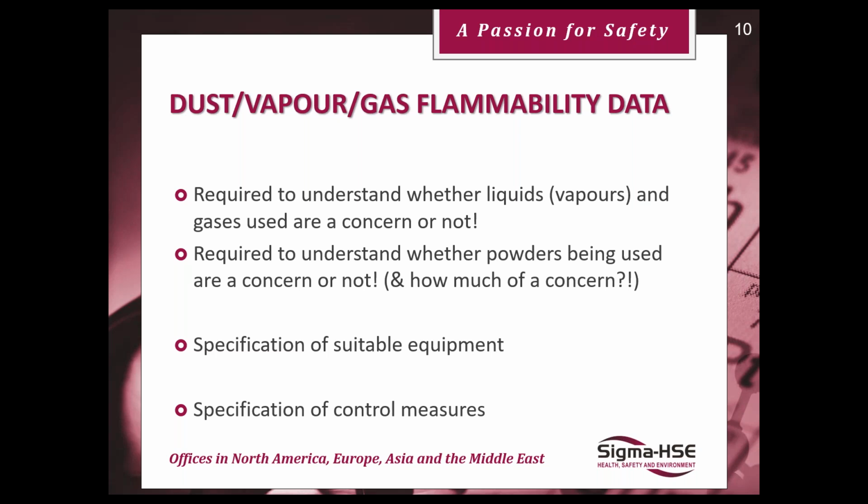And this is where you'll have heard about ATEX certified equipment, ATEX switches, ATEX valves. These are all built to a specification that reduces their probability of ignition. Doesn't eliminate it, but it tries to reduce the probability of it. Okay, and we need data to be able to do that. We need data to be able to design our vents correctly or our containment systems correctly.